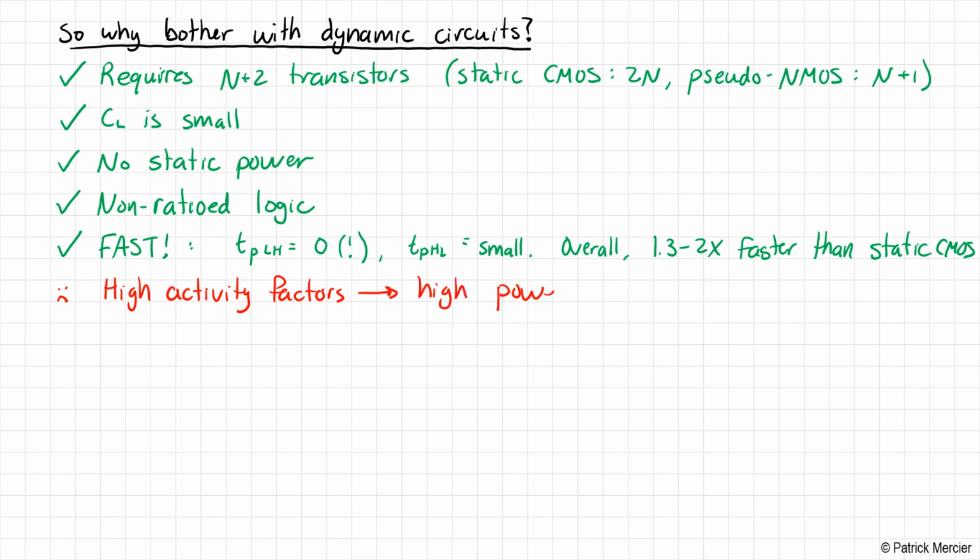Dynamic logic is fast, however, there's a price you pay for that speed, and that's in terms of power consumption. In addition, we have a downside related to noise. Leakage is a problem. We have to refresh logic values and so on. There's charge sharing issues that we're going to talk about momentarily, etc. So there's a whole host of problems.